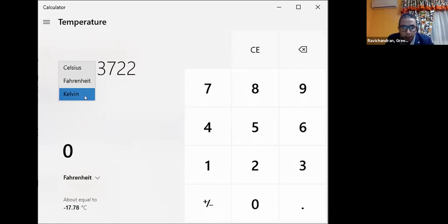Rankine is not here. So in some problems with British units, the temperature is given in Rankine, and you need to continue by Rankine or Fahrenheit. Or it is given in Fahrenheit and you need to continue by Rankine. So the conversion between Fahrenheit and Rankine should be in your mind. For example, this is from exam 4, I think. If Fahrenheit is negative 30, how do you continue? With the 460 conversion to Rankine, the degree used in the calculation is 430.